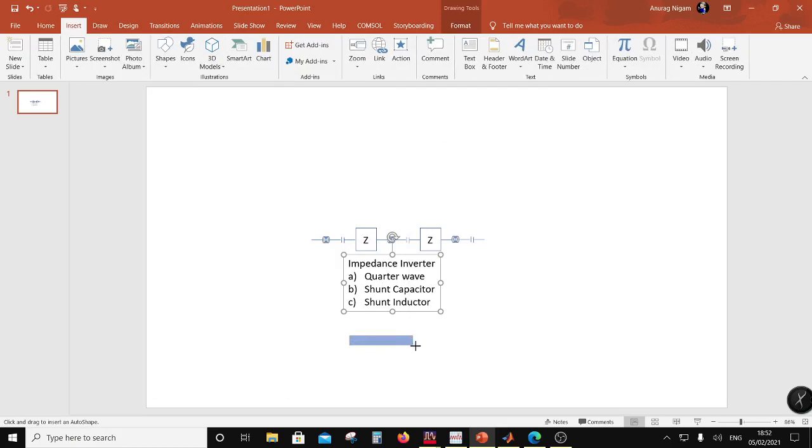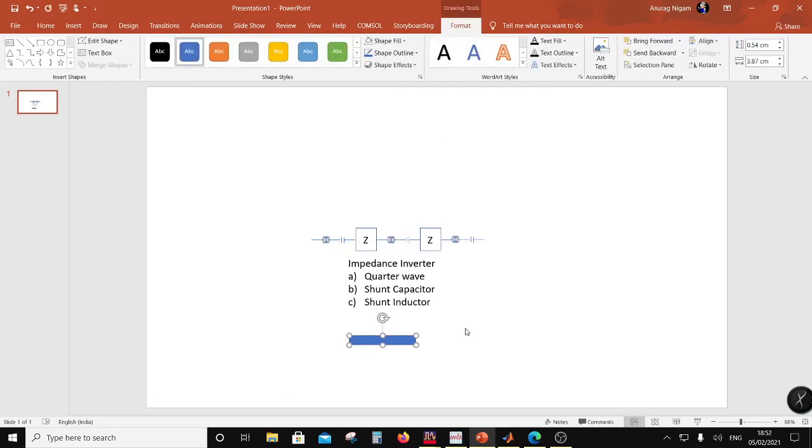this can be as simple as a line, right, of a certain impedance, and then you can have a coupling between them, right? So you can have these lambda by 2 lines which are acting as resonators, but then you can have a coupling between them of some form, right? Now this structure can be used to implement this. Another way to implement this would be, I can implement the shunt portion of it, right?